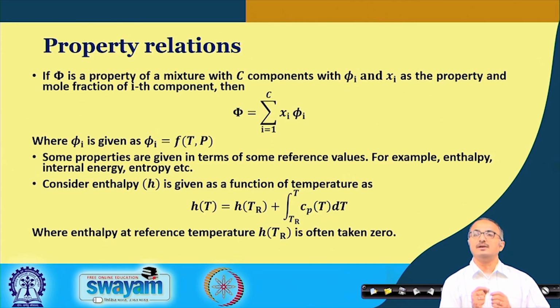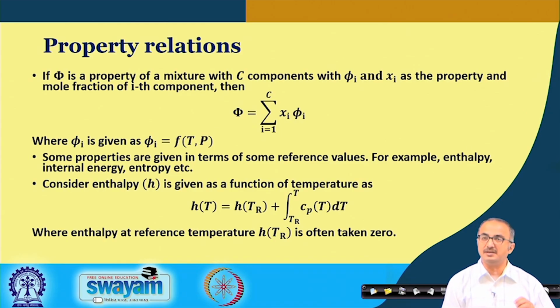So, whenever you are taking values from different sources, make sure that the reference temperatures are the same. If not, you are going to commit a mistake, and whatever result you obtain will also be erroneous. That is the very important point one should note about the reference state.